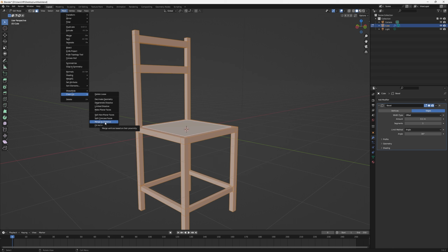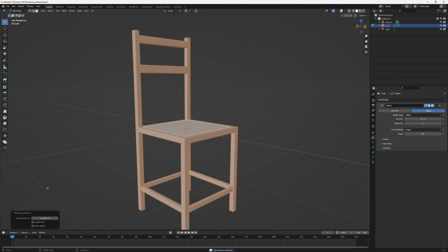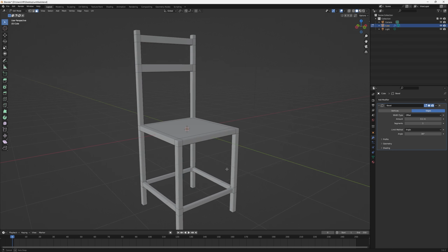This step will clean up those extra polygons. So let's try this one. Now you can see there's a little menu pop up on the bottom left, indicating how large a distance can be used as the threshold for merging these extra overlapping components. I think the default value should be good for cleanup purposes.